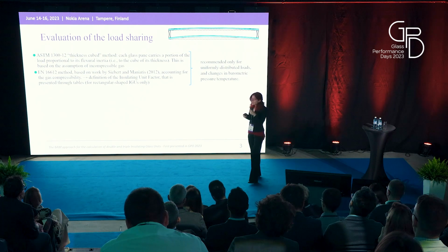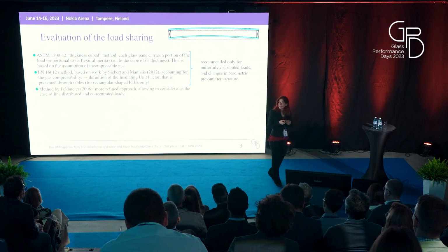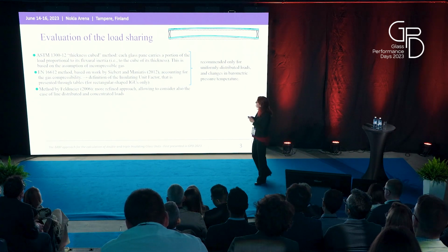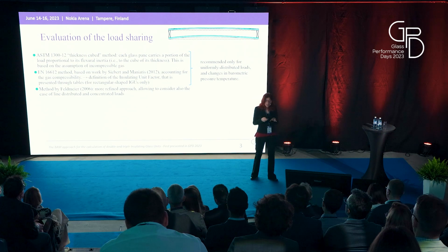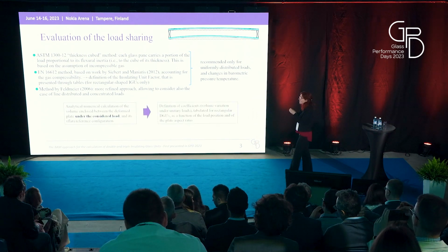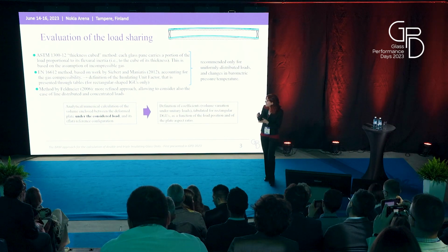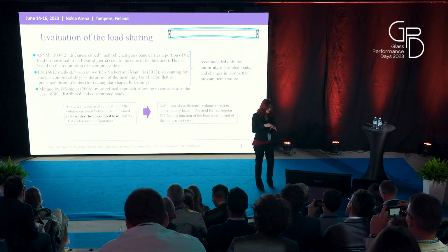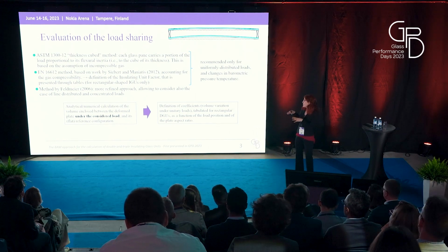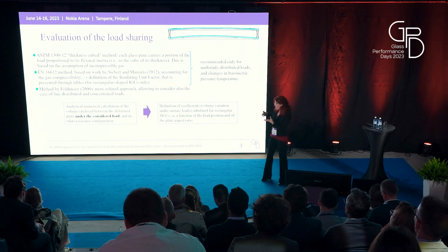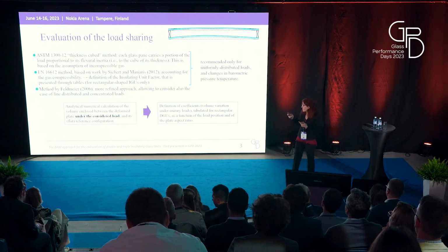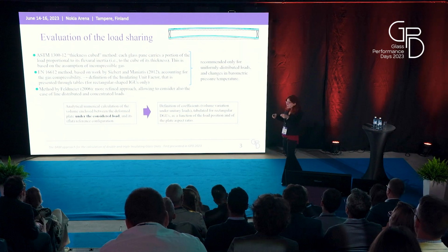for uniformly distributed loads. A more refined method is that proposed by Feldmeier, that allows consideration also of the cases of line-distributed and concentrated load. This is a very accurate method, but it is quite cumbersome because it requires the calculation of the volume enclosed between the deformed shape of the loaded pane and its initial, flat configuration. And this calculation should be done for each load case, as a function of the load position and so on.